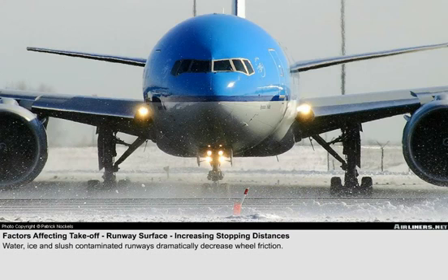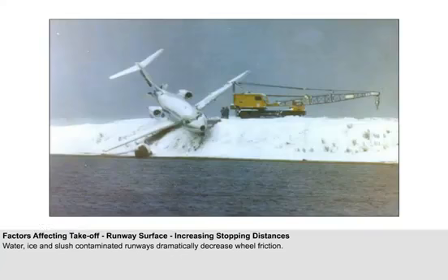There is potentially an even greater effect on the aeroplane from ice, water, and slush on the runway, other than the effect of the increased drag on the wheels. These substances will dramatically reduce the friction between the wheel and the runway, acting similarly to a lubricant. Whilst this may not seem too much of an issue whilst trying to get airborne, it does present an enormous problem when trying to abandon the takeoff and bring the aeroplane to a stop before the end of the runway.